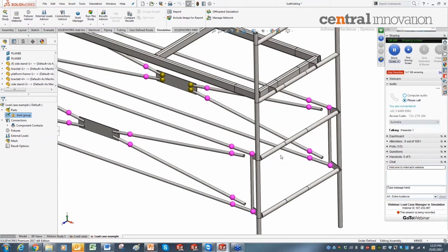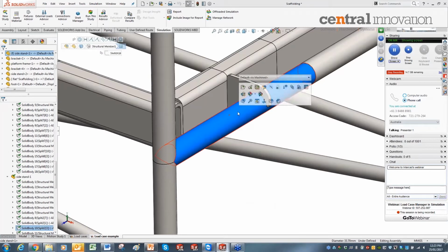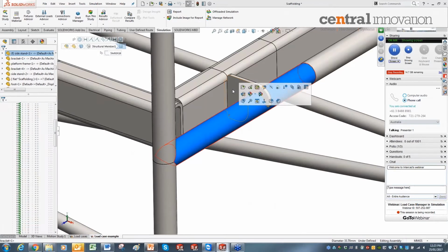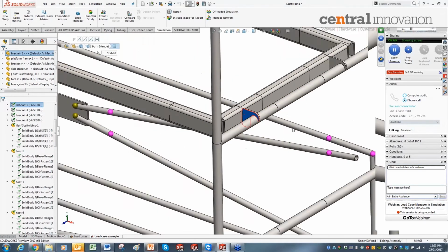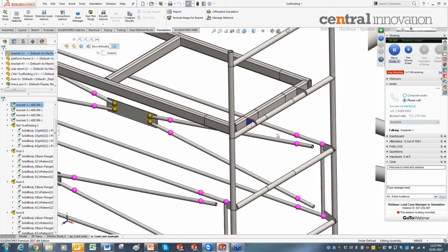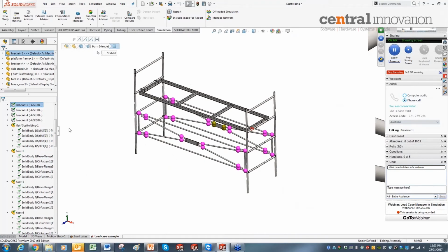And in here, I have this bracket. This bracket can translate on the tube surface, on this surface over here. I mean, this bracket can be moving on this surface. It will be sliding on this surface. So I have to define no penetration conditions between the bracket and the tubes or the beams. So I need to create lots of contact conditions.